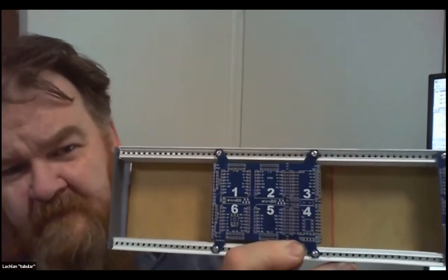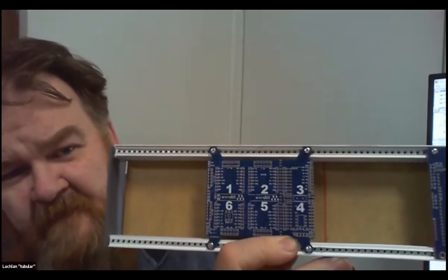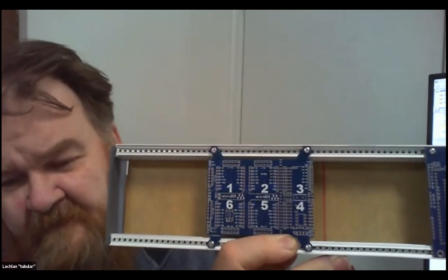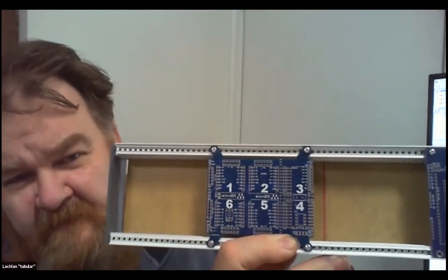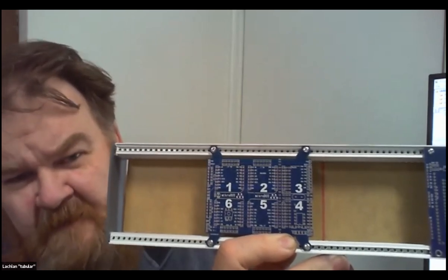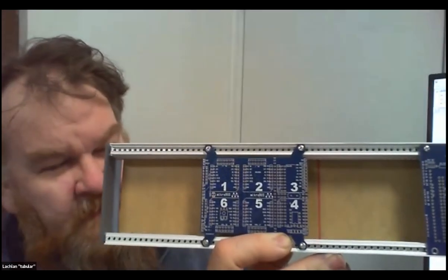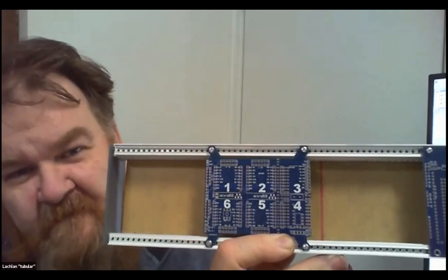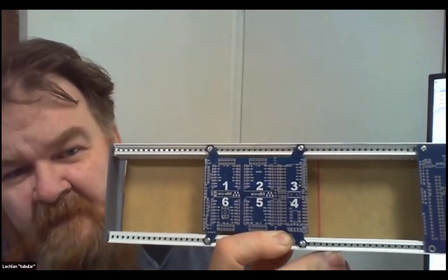A lot of the official Mikroelektronika products multiplex up some of those pins, so you might have I2C going across multiple Clicks, but with the P2 you've got enough pins to break them out individually. It takes advantage of the P2's pin flexibility to have 12 pins going to each module.